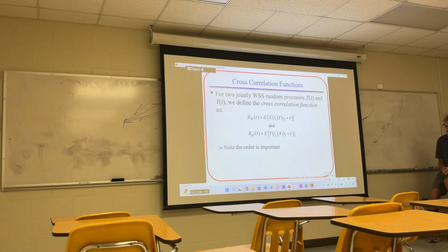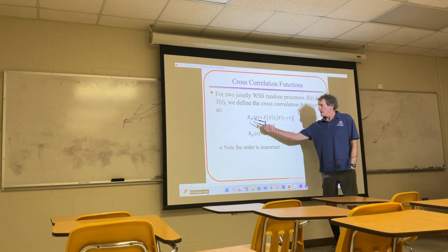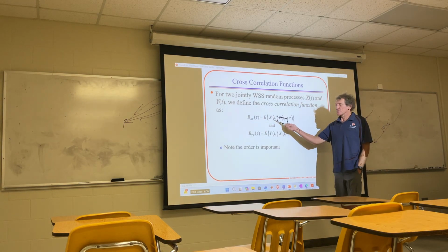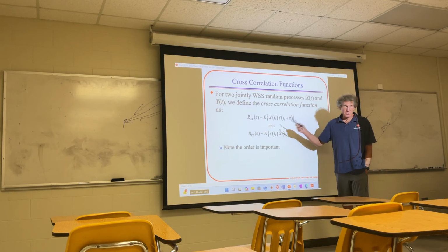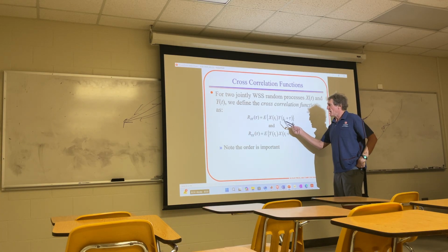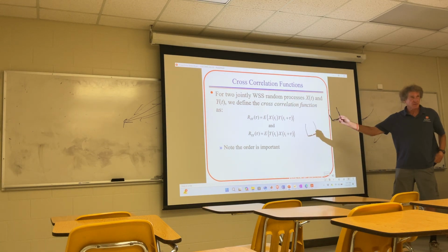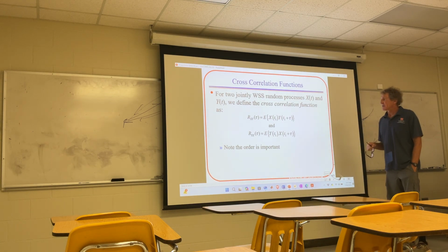All right, so this is cross correlation in a nutshell. Same thing as auto. The only difference, and I'm going to point this out, they have x, y. X is the one that is not going to have the skew. So it's the first function, x of t, and it's going to be y of t plus tau. Tau is the skew, or the amount you're going to push something and then do this integral.